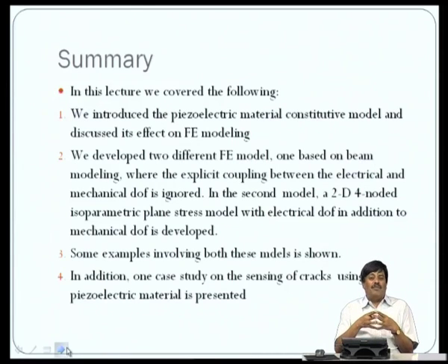So, in microsystems we need the modeling of electromagnetics, electrical field, electrostatics, where Maxwell's equations need to be modeled, the wave equation for mechanical systems, the Navier-Stokes equation for the fluid system, and Fourier's law for the thermal systems. So, it does not matter what the governing equation is; the approach we have derived is exactly the same, only the meaning of the dependent variable changes. So, in short, the finite element modeling we have developed can be exploited for all other domains which are prevalent in smart and micro systems. Thank you.